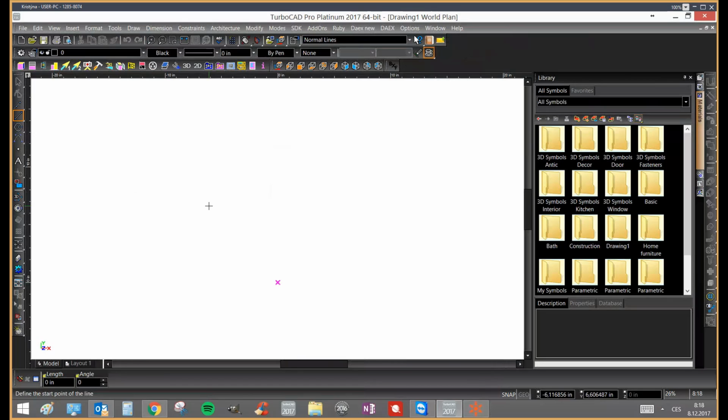Okay, great. So if you install TurboCAD and the TurboCAD Furniture Maker on a user's PC, it is good to adjust the icons to add the standard views because they are used a lot, and also to put there just three renderings: the quality rendering, super-hidden lines, and wireframe.